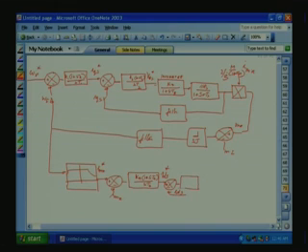If we are using a space vector PWM, then we require VDS. So one more PI controller. So this is K5 into (1 plus ST5) by ST5. This will give VDS reference. Again the converter, VDS reference, the same converter, that is the same K3 by (1 plus ST3).